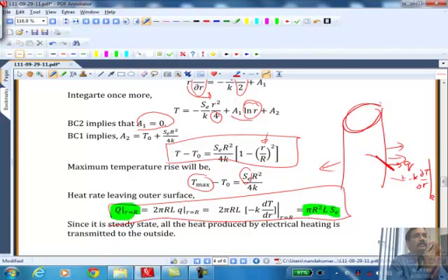So that's going to be equal to Q at R, the heat flux at R. What are the units for heat flux? So many joules per meter squared per second. Okay, so I need to multiply that by the surface area. The surface area for the cylindrical shell is 2 pi R times L.